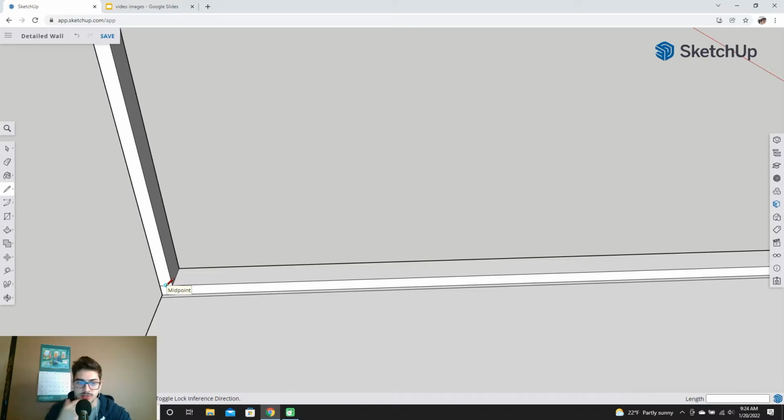There are some materials where it's actually allowable. You can go up to like 24. Some people will overdo it and do 12. Some exterior walls, different areas, code is different. But 16 inches is pretty normal. They say on center, it's exactly the same thing conceptually as on right edge, on left edge. It doesn't matter. It just means if you are at the middle of a stud and you go 16 inches, you should be at the middle of another stud.